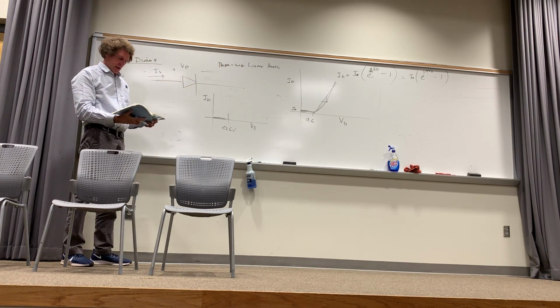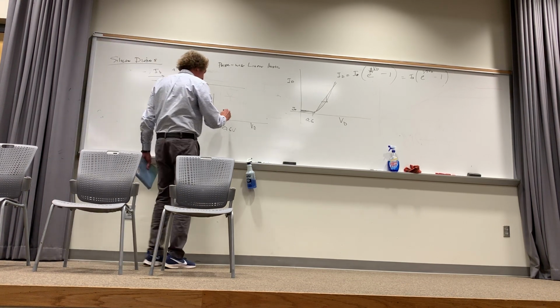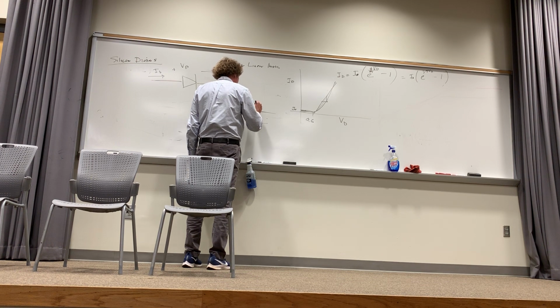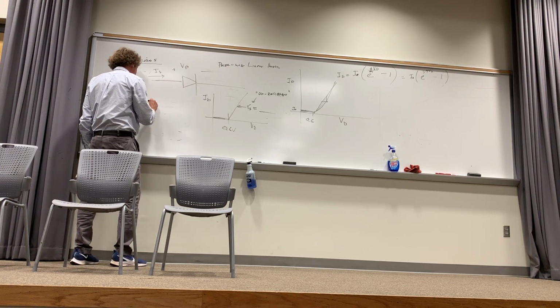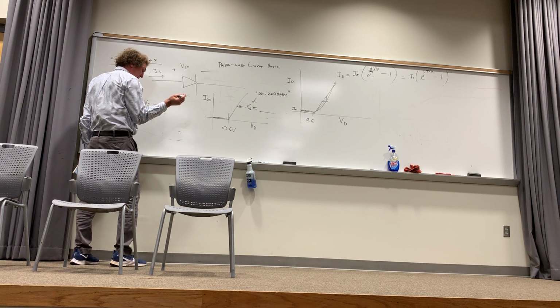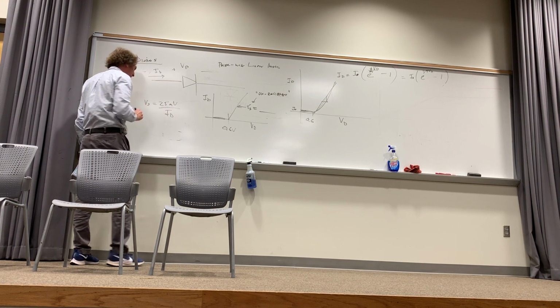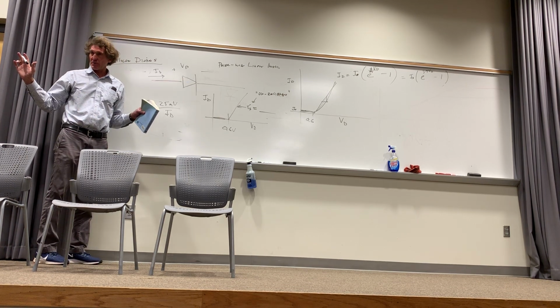This is for silicon only technology. Then you're going to have an on resistance here, and this is modeled by just RS as a certain value. Call it the on resistance. Now, RS technically is normally 25 millivolts divided by the actual diode current. That's the actual RS used for an exact model. For us, most of the time, RS is just given as like 40 ohms. All right, follow me in this class?